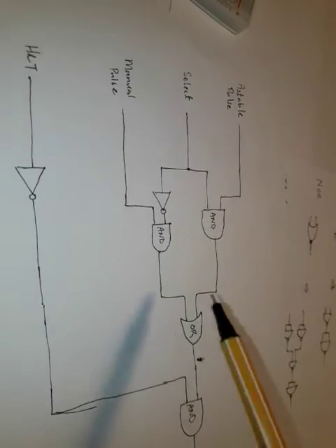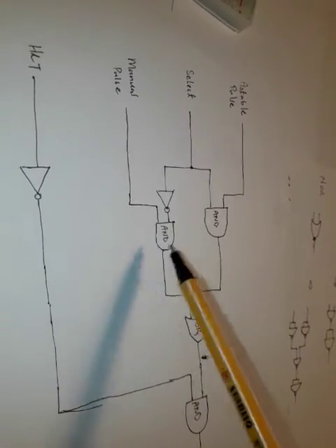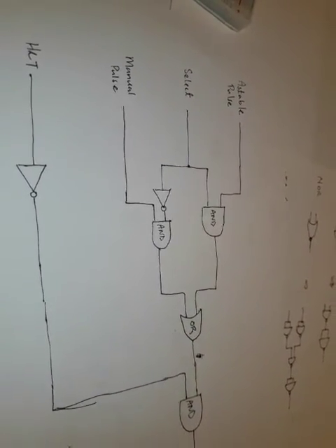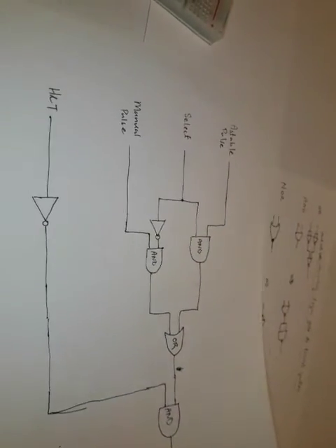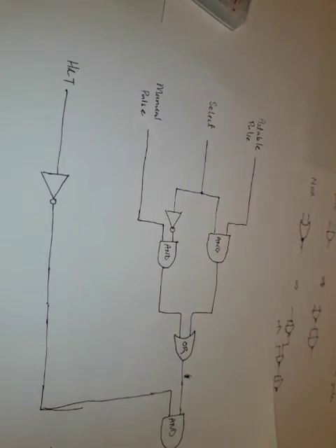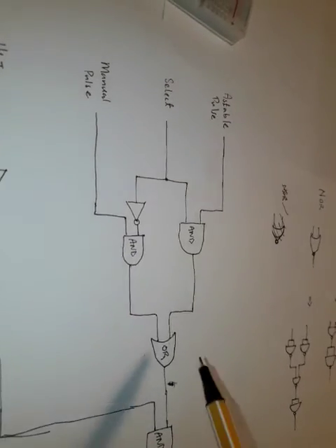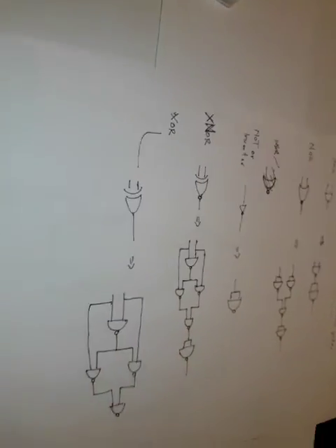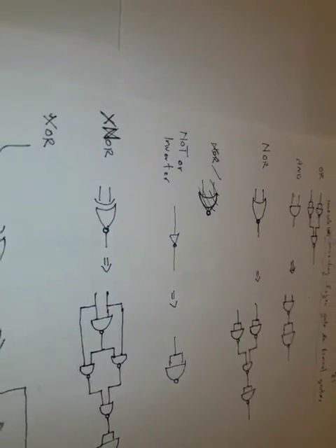So now it means I'm going to need 2 AND gates and 1 OR gate at the moment, but unfortunately I don't have this gate. But the beauty of it is you can build any gates with the NAND gates, which is why the NAND gates are referred to as the universal gates. And here you have the equivalent of the NAND gate for the OR, the equivalent for the AND gate, and the equivalent for the NOR gate.